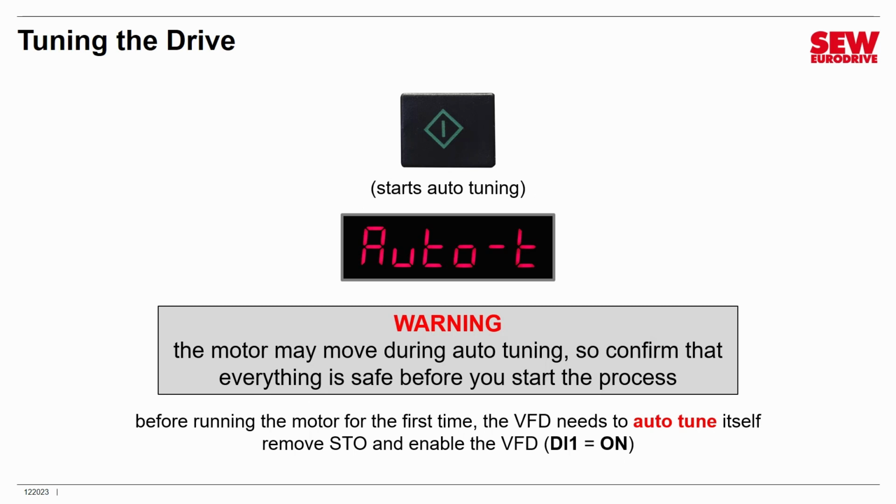Then press the Start button, and the display should change to Auto T. You'll hear some funny noises coming from the motor. This takes somewhere between 30 seconds and a minute, and eventually it will change to stop, indicating that it's finished. And at that point, you can run the motor.